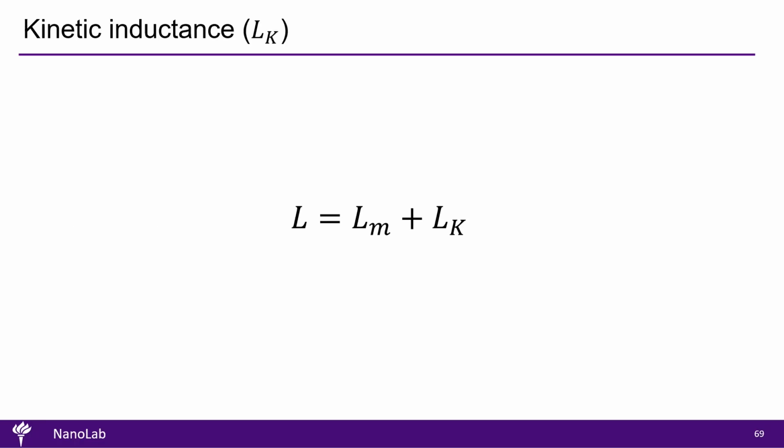Inductance, L, which measures a conductor's tendency to oppose changes in current, has two components: magnetic inductance, Lm, and kinetic inductance, Lk. Magnetic inductance arises from the back electromotive force induced by the magnetic field created when current changes in the conductor. Kinetic inductance, on the other hand, is due to the inertial mass of charge carriers and an alternating electric field. In normal conductors and typical applications, magnetic inductance dominates, but in certain cases, particularly in superconductors and thin films, kinetic inductance can become the dominant contribution.